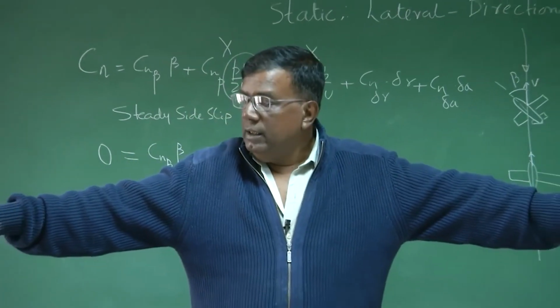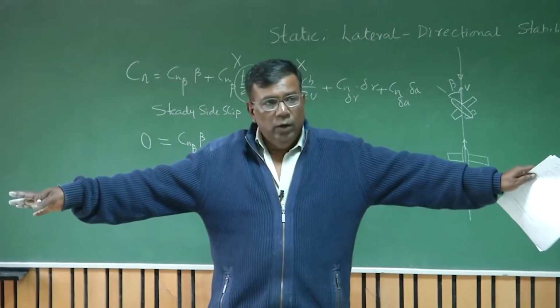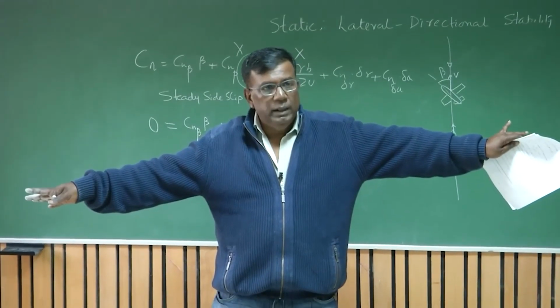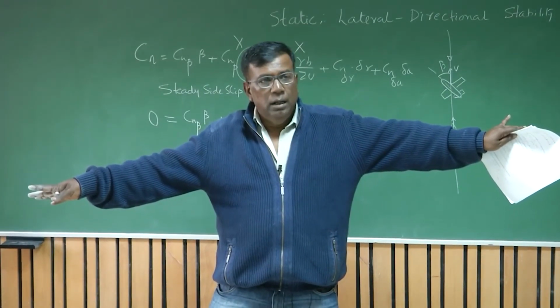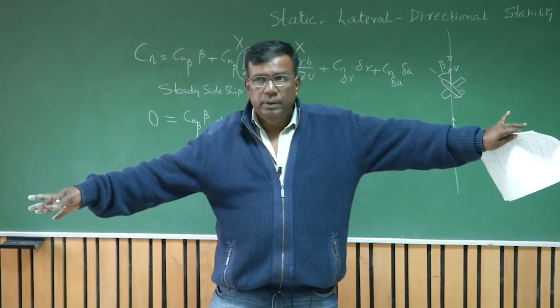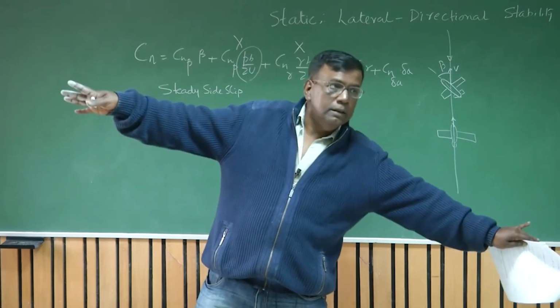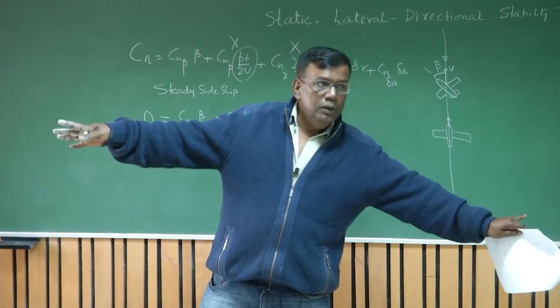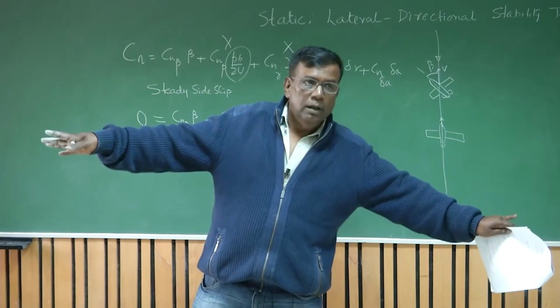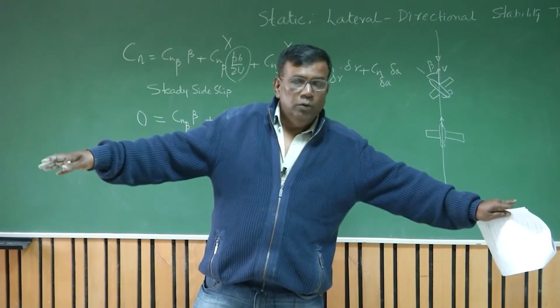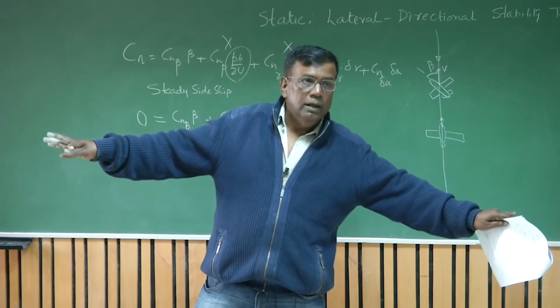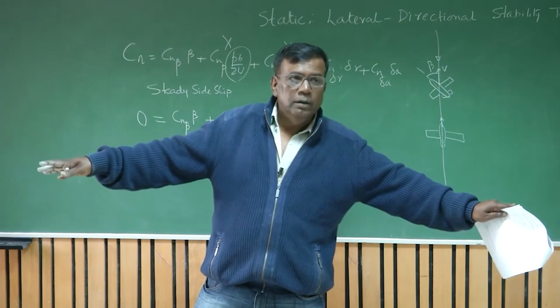I have deflected the aileron here down and then up. So which way will it bank? Down, up, like this. As it moves like this, which wing is having more lift? This one. Which wing is having more induced drag? So what will the plane do?